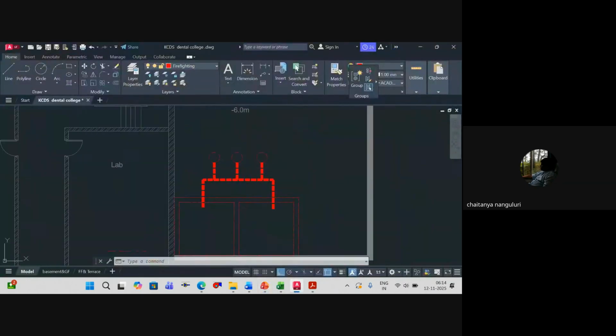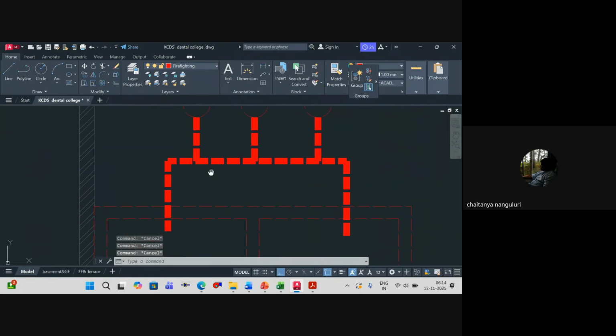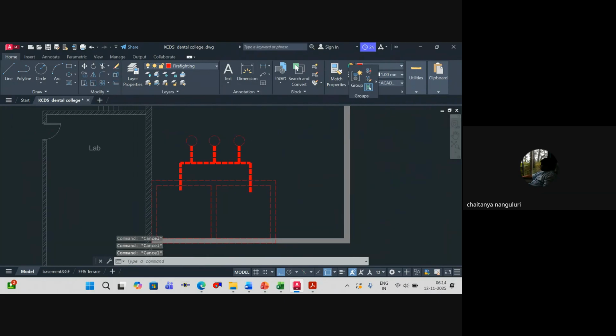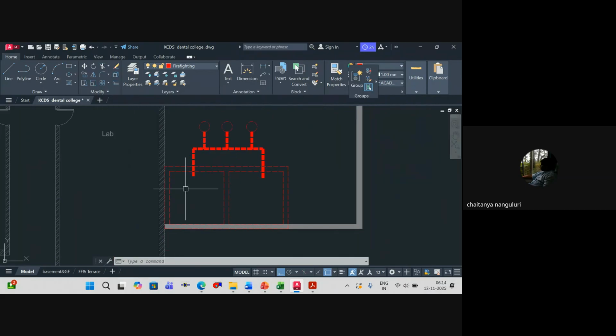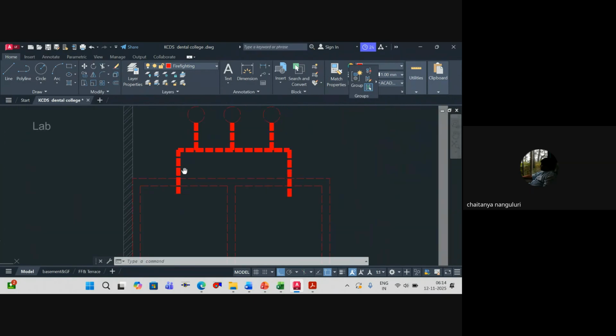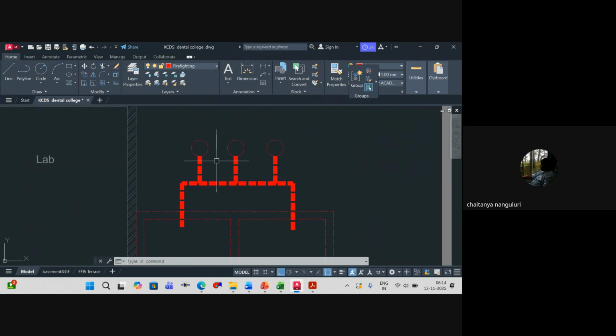Fine. So now we have these pumps. From these pumps, at the end, basically here you'll have an isolation valve. Compared to a butterfly valve, I would prefer a sluice valve because you have a high head and a large volume of water coming. So I'll always prefer a sluice valve in the main line. Here you select one sluice valve, here you'll select one sluice valve.